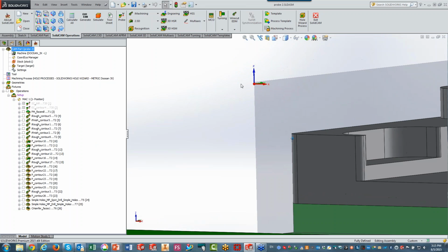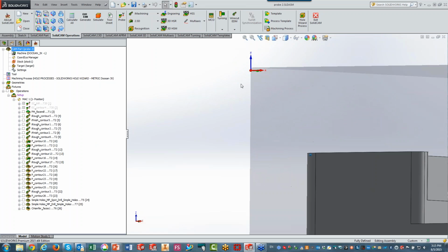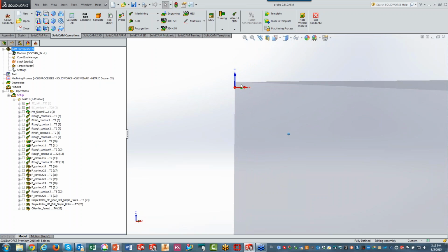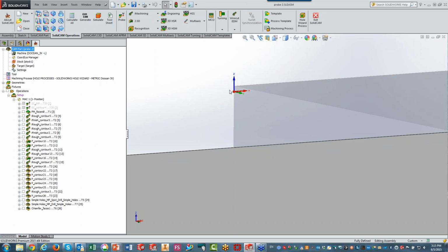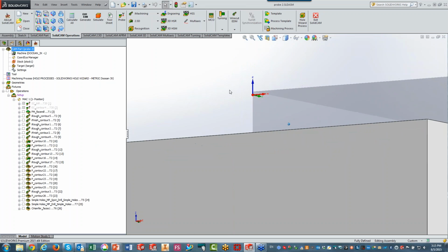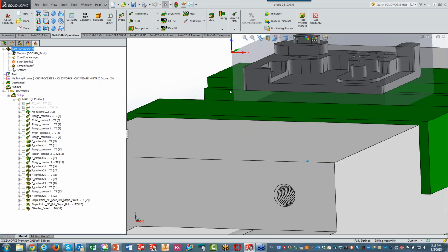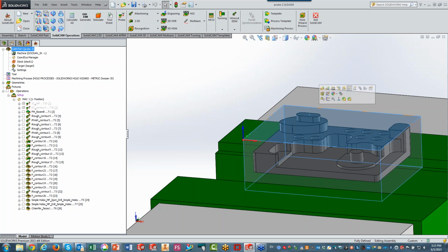But if I look in the Z level, I'll try to zoom in a bit. You can see it's a little lower, and I can tell you right now, it's 0.3 millimeters above the actual part itself, from that surface to the top surface over there.